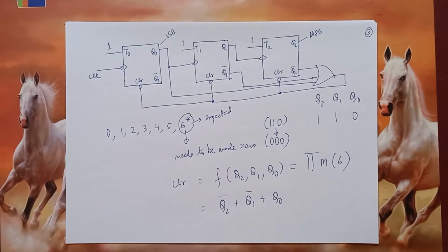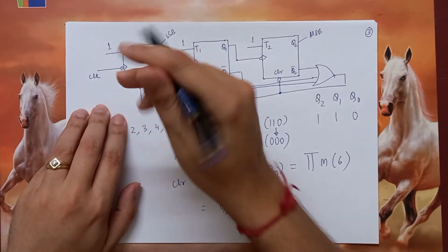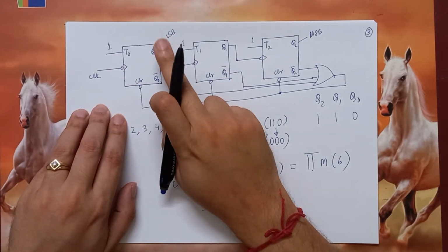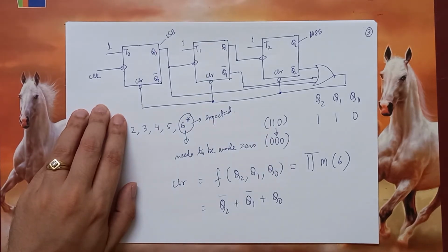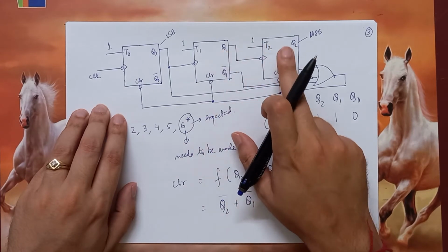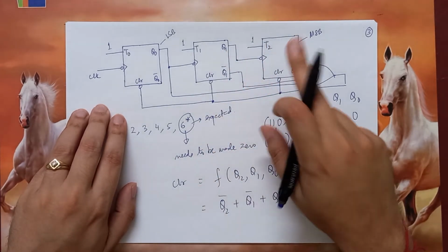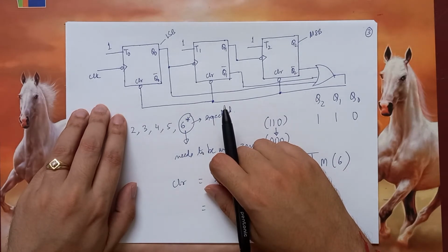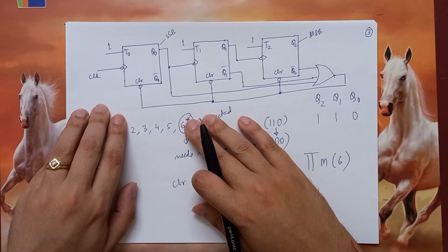Now, when you say the word ripple carry or ripple counter, once again we are taken back to the fact that these circuits are essentially slow circuits. When the clock comes to the first flip-flop, until the time Q0 is ready, the second flip-flop will not get the clock. Likewise, until Q1 is ready, the third flip-flop will not get the clock. So ripple counters or asynchronous counters are very slow counters.